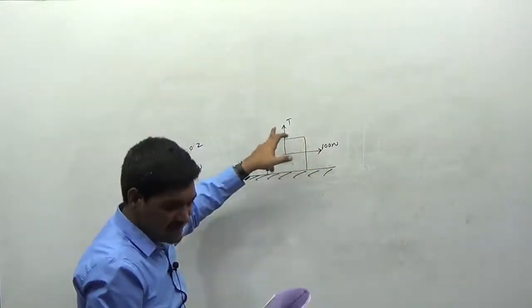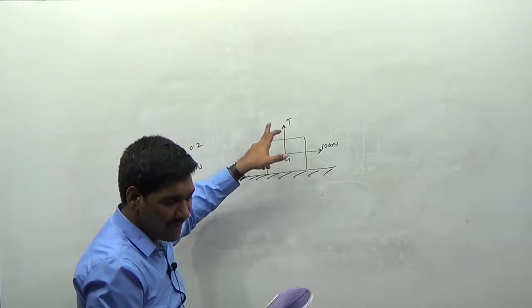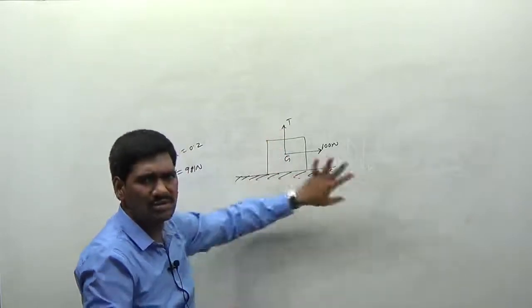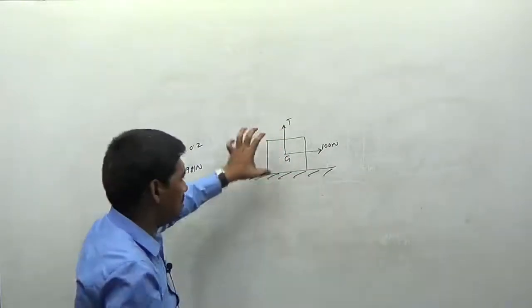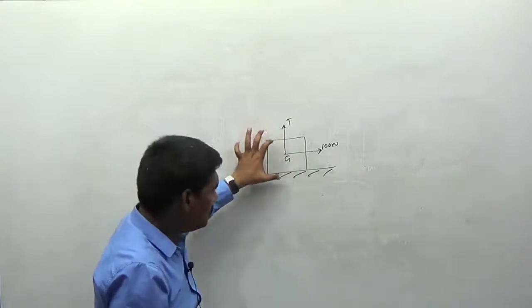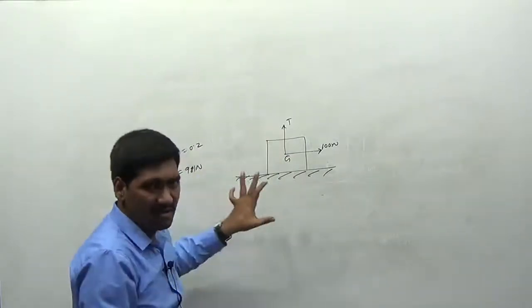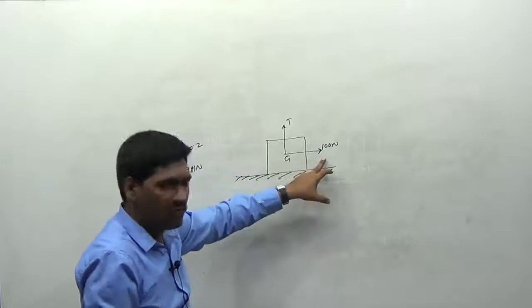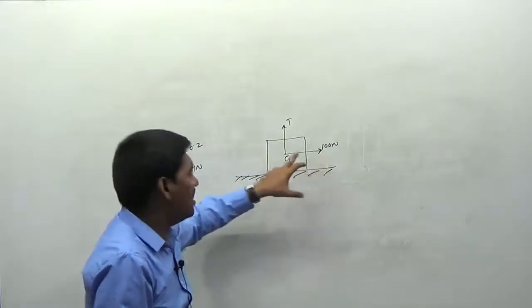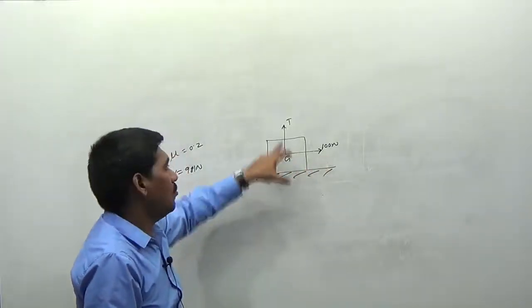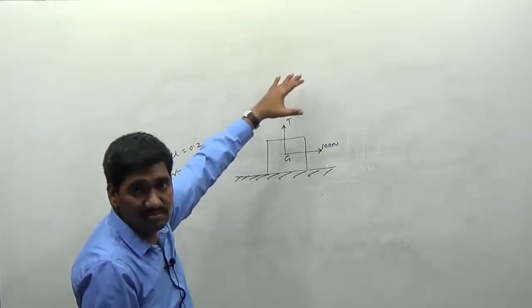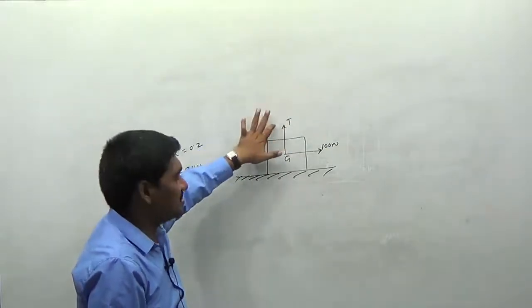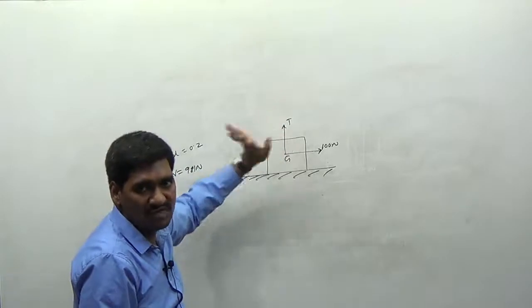So what will be the tension in the cable if the man is just able to move the block towards right? Okay. Now see here, this is the block. On this, the weight of the block is given as 981 newtons. On this block, we are applying a force of 100 newtons here. And this block is connected vertically with the help of some string. So therefore what we can say, the force in the string will always be equal to the tension force, right?